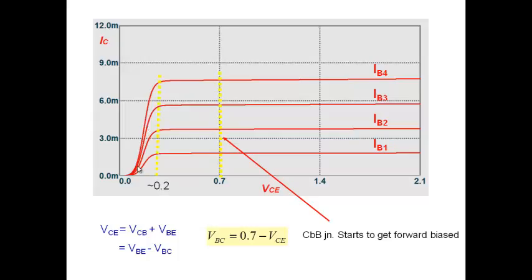All right. So when we are thinking of our transistor, we said we want our transistor to operate in forward active mode. We want it to be here. No, we want it to be here. Strictly speaking, forward active mode stops here. So you may say, well, if you don't want your transistor ever to go into saturation and you're very strict about it, you'll say, I don't want my VCE to go less than 0.7. That's what you would say. Never let VCE, the collector emitter voltage in your transistor, fall below 0.7. If you ensure that, you are always in forward active mode.